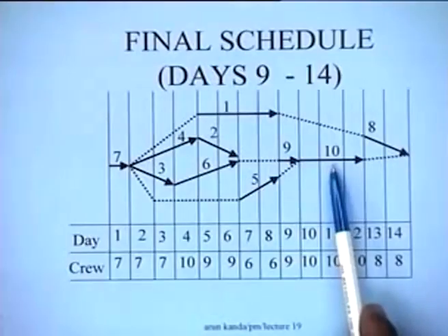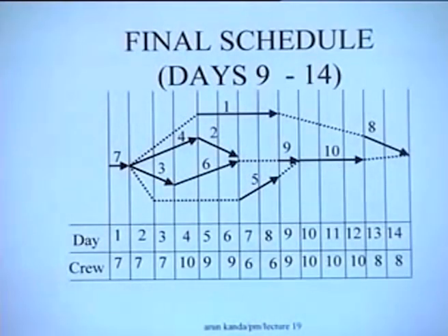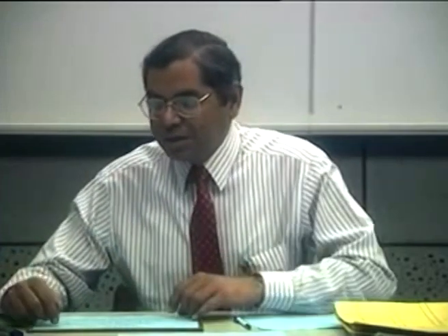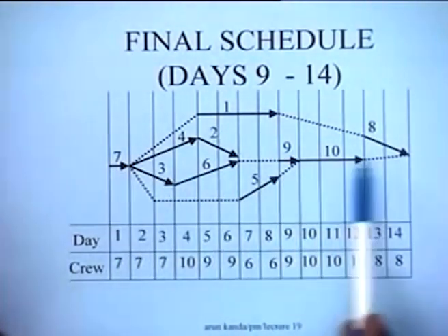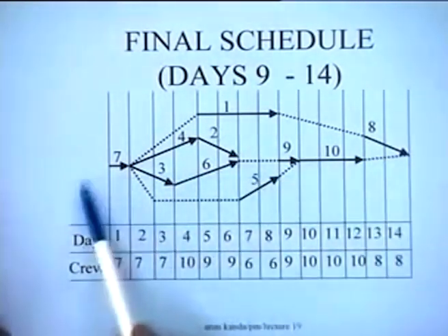This is a very interesting thing which has happened, and in fact in all limited resource allocation problems you do not typically have a critical path in the conventional sense, and the notion of the critical path is however replaced by the notion of what is called a critical sequence. Now what is a critical sequence? Let us try to examine for this particular final, that means can you identify some set of activities whose durations add up to the project duration.